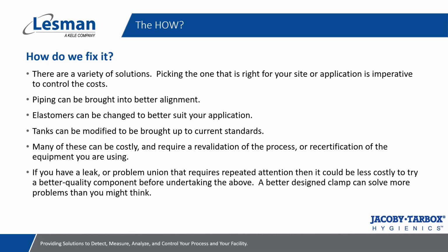If it's a gasket, if it's a piece of equipment, have contingency plans for things like, hey, we identified that gasket works in 90% of our connections, but in 10% of the connections, we also need a different seal method or a different seal material so that we can accomplish that effective seal without having to start over after we've already written the playbook.